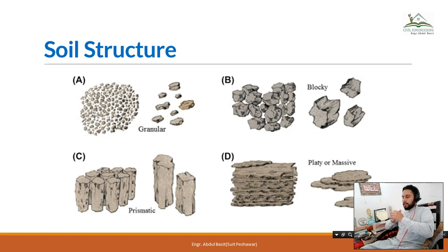So simply, we can say the soil structure is that type of engineering property which may affect the rest of the engineering properties, like the shear strength, the compressive strength, the bearing capacity of the soil, and different other engineering properties that we may need in the design of foundations and investigation of soil for our engineering purposes. This is a simple picture I am displaying here, in which we have different types of soil structures.